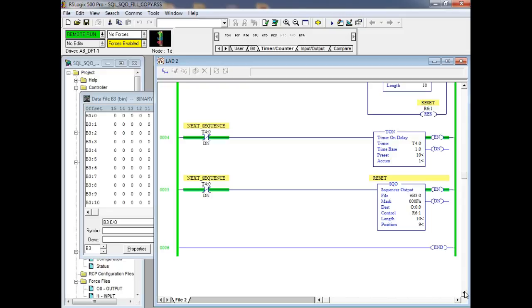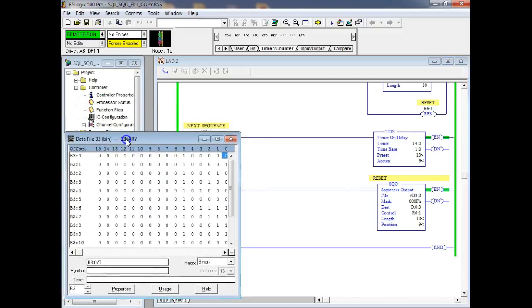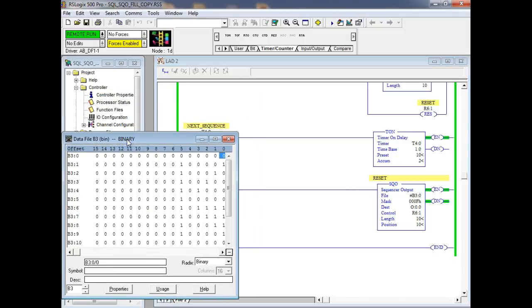How do you know it's actually copied in? Because it's running. I don't know, maybe I don't understand. So all you did is go to the B3 file and change over. Yeah, what we did is we went in, and first we cleared out B10, that's what you need to do, clear it out first, understand. If you don't clear it out, and you don't use all 10, then it'll keep whatever's in there before. So I'm using the file field to clear out that B10 that I'm using.